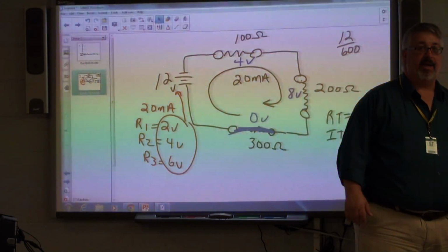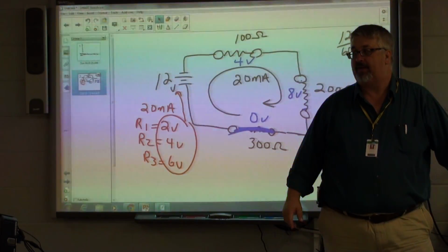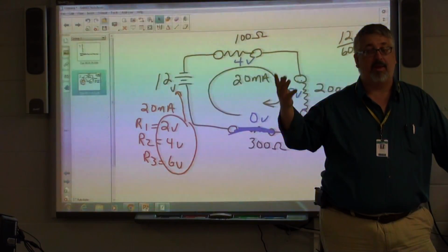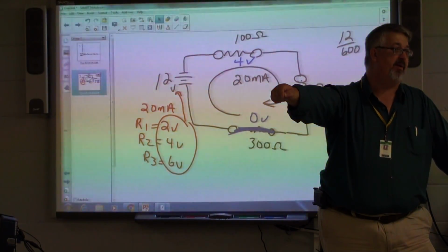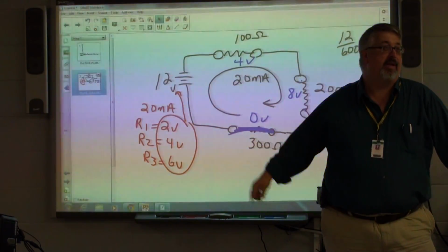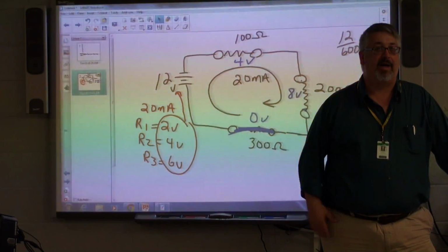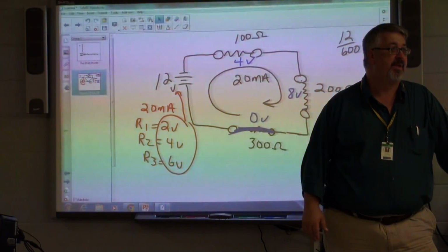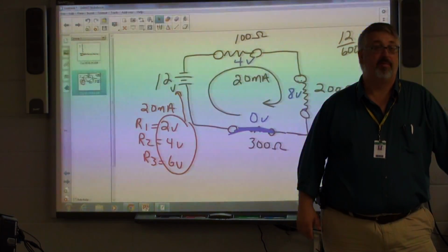And the other thing that can happen is that an operator mixes the resistors up. We had some boards we built back here where the resistors were mixed in the cabinet. I may reach into the 1K resistor cabinet and find a 1 ohm resistor there, and that's almost a dead short. So we can see the same characteristics just by applying a wrong resistor in there. 1 ohm is not far from a short. It would be such a little drop we would barely see it.